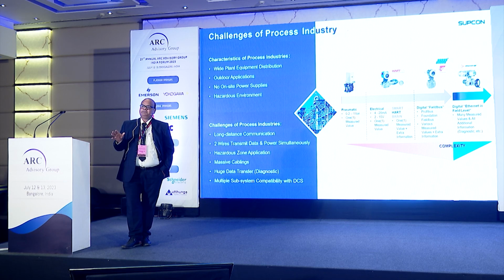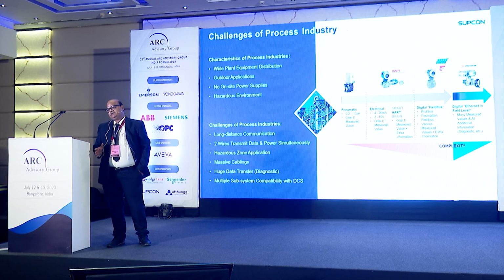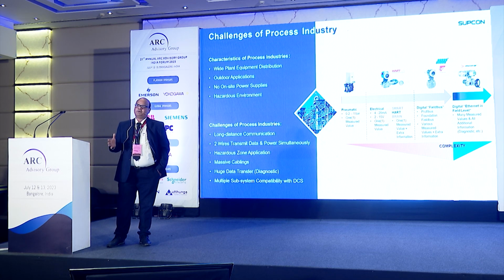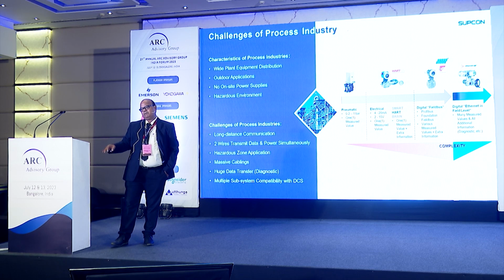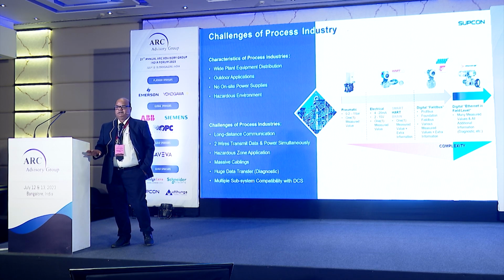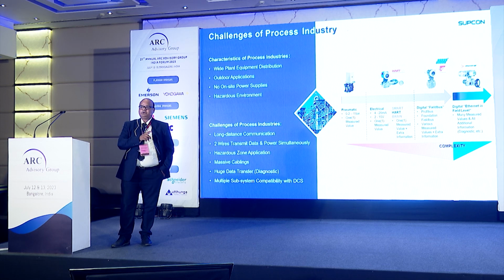In this waste to energy plant, the basic problem is that when we store the waste, leachate comes out. Leachate means the drops of water coming out of the waste. It is in the pit at -9 meter. And again, we have to control the pollution which comes out of the chimney.